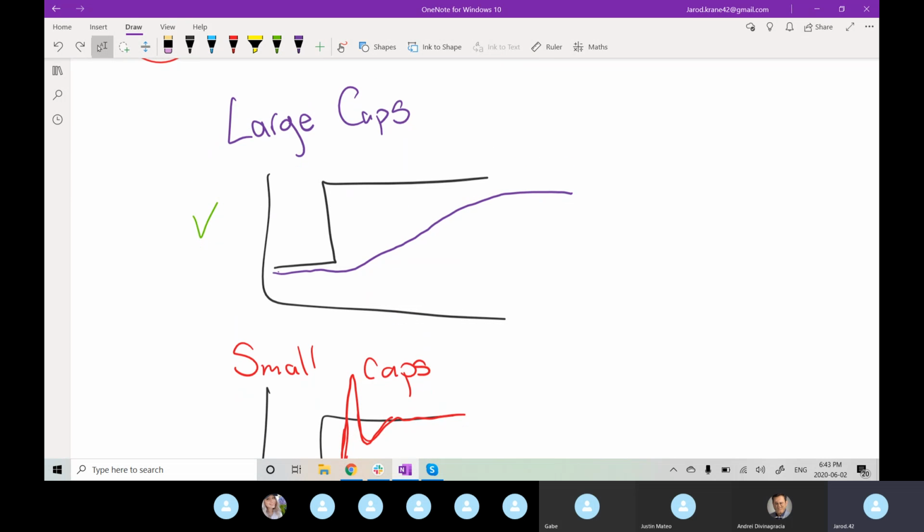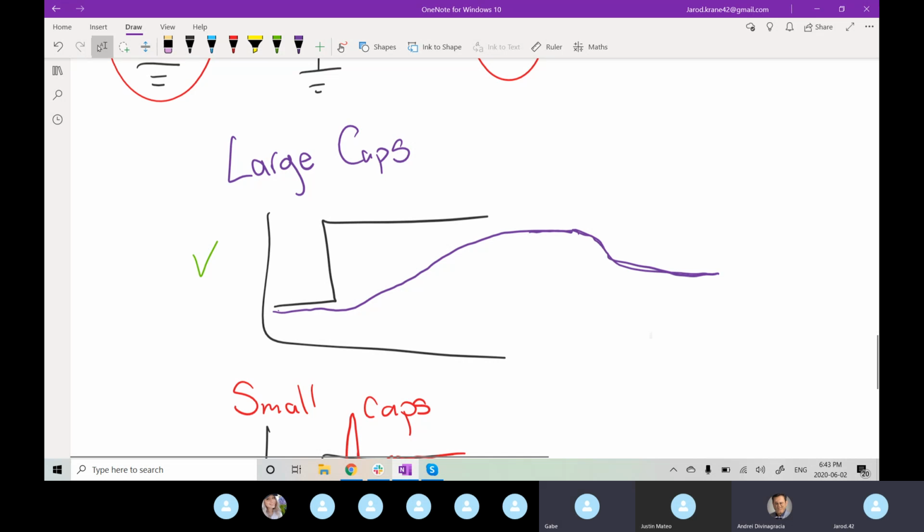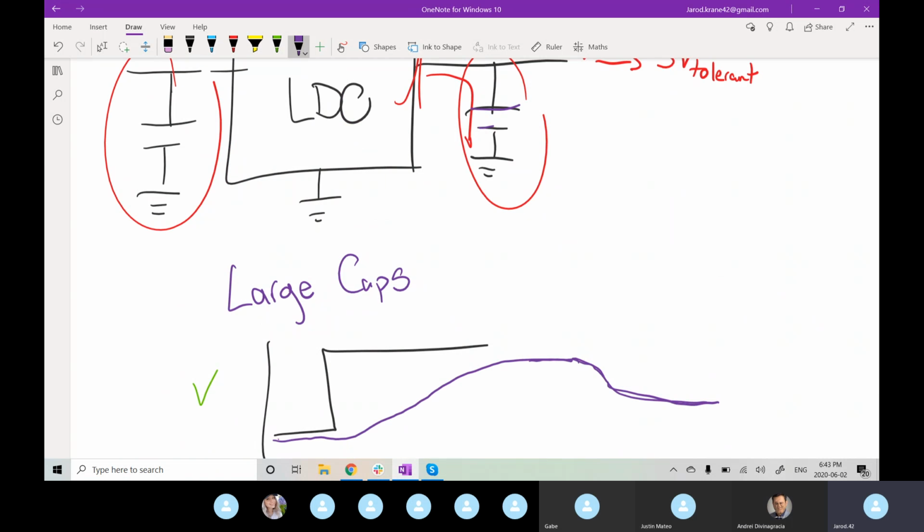Yeah, with high current loads, you'll often tend to see what's known as voltage sag. That is, at high currents, your voltage will dip a little bit if you're holding at that high current. So if we have large external caps, they're able to push back out some voltage to help you out and keep it where you're supposed to be.